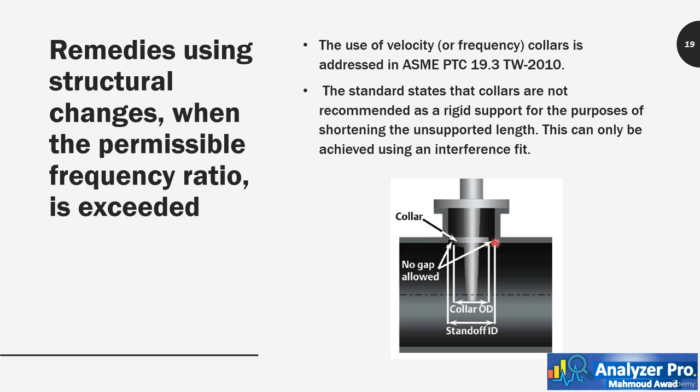This could create stress risers in the probe due to the indentations, or it could eventually break welds that may be located near the collar. The collar must be an interference fit to be effective.